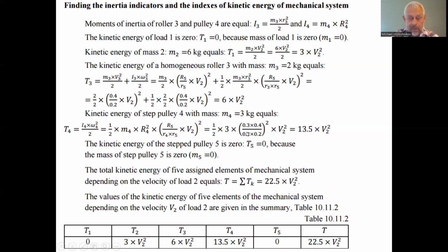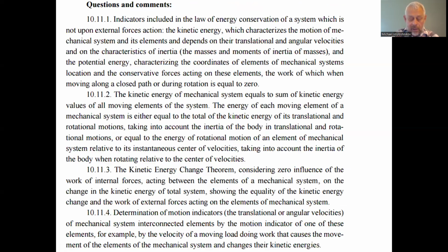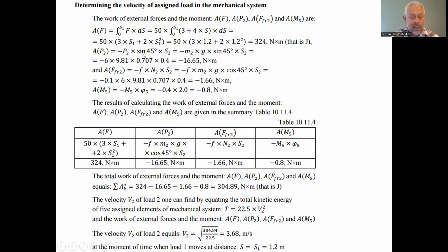So to do that, we multiply by sine alpha, the sine of the angle of the inclination, finding the work of the weight, finding the component of the force parallel but opposite in direction to the motion of this second load, and we multiply by the cosine of 45 degrees, the same magnitude, square root of 2 divided by 2.